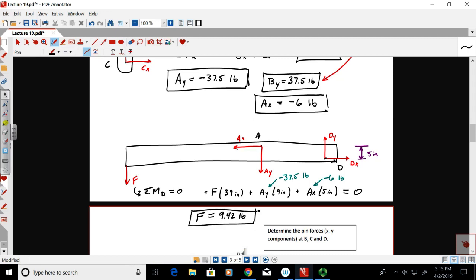So you can see here there's not really that big of a magnification. There's a little bit of magnification of force. This mechanical device does give me a little more lifting force, but not by a lot. It's not like a huge difference. If I could pull with 60 pounds, it would give me 94. Yeah, that's nice. It's like a 1.5, 50% more. Well, that's cool, but nothing huge, right?